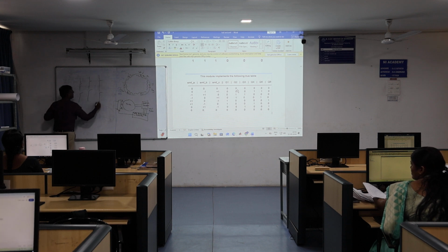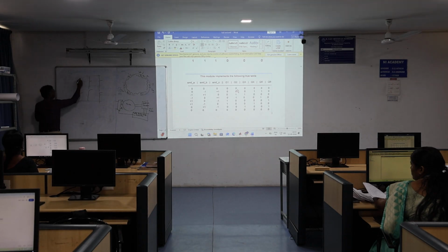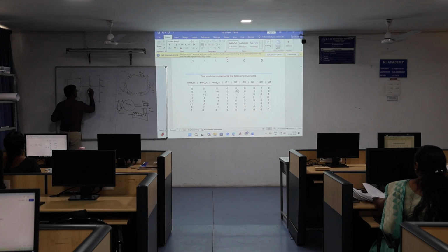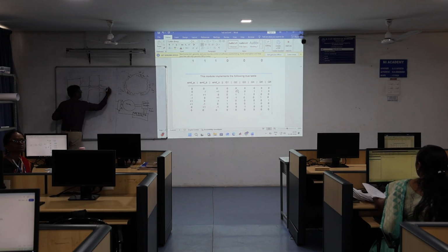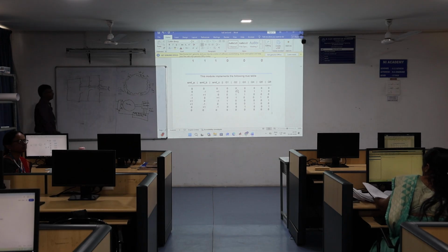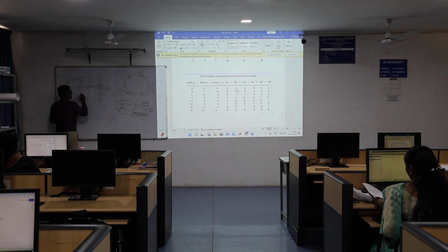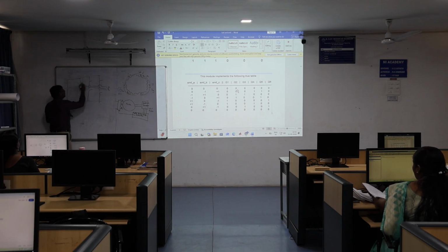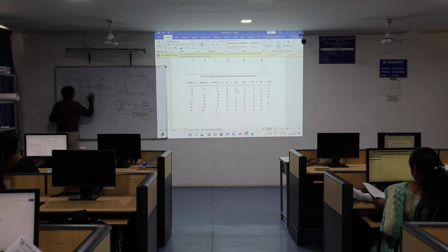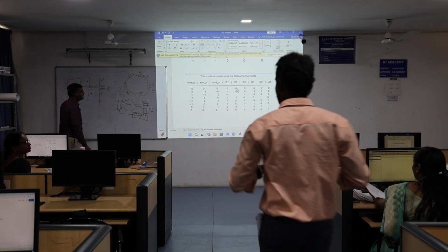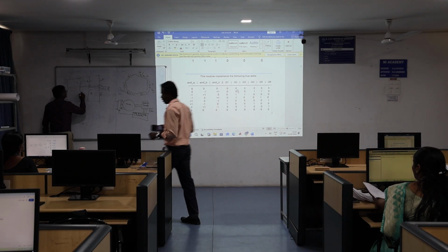You have an inverter where the inverter is powered by means of DC supply and the output is AC in nature, A, B, C. What we have to do is we have positive switches here and negative switches here. 1, 3, 5, 6, 4, 2. So what happens here is 4 and 5 are fired.